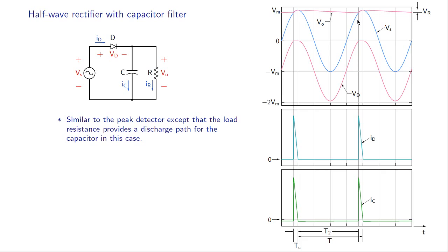And this process is instantaneous because the time constant for this charging is very, very small. Why is it small? Let's look at the circuit from the capacitor. What we see is this resistance and the diode resistance in parallel, and that is of course nearly equal to the R on of the diode, which is very, very tiny.